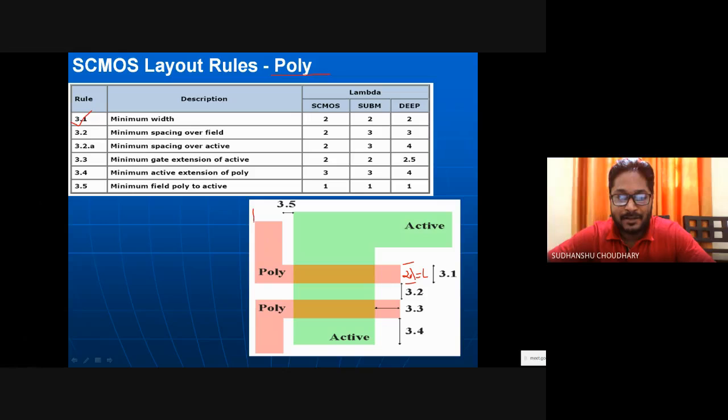I say that this polysilicon has to be connected to this metal line. They are overlapping now. Let's say this is my metal one and this is poly, obviously. So I need to connect them. I'll drill a hole in between them, maybe here, and then in that hole I'll fill this contact material. Contacts are represented by a cross. So I have a contact over here between metal one and poly.